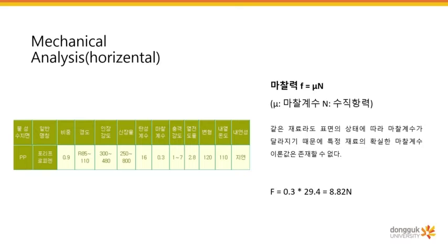The investigated friction coefficient of polypropylene was 0.3, but we kept in mind that the friction coefficient depends on the shape of the product, even if the same materials are used. So the investigated value 0.3 was used in the calculation, but the exact coefficient will be obtained through a final test in the future.